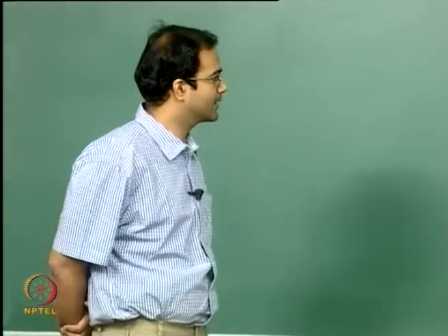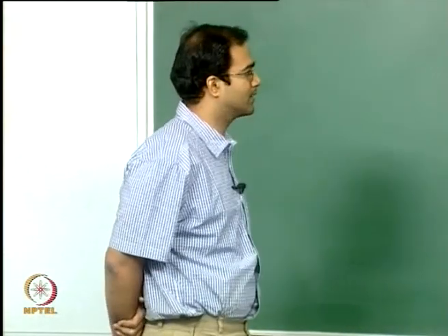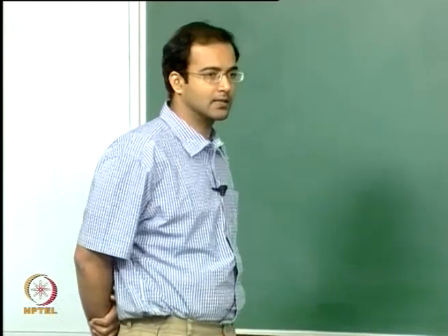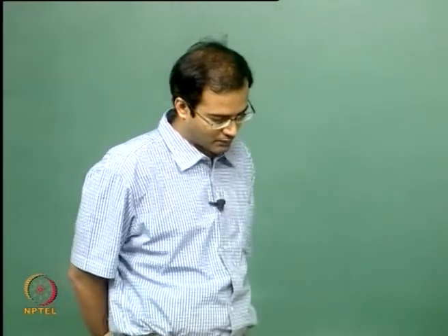So, good morning all of you. We are continuing our derivations for similarity solution to different kinds of external boundary layer problems. So, we had looked at Falkner-Skan solutions and the corresponding heat transfer solution associated to Falkner-Skan velocity similarity solution in the last class, and we had taken some special cases for that where m equal to 0 indicates flat plate and m equal to 1 indicates stagnation flow.